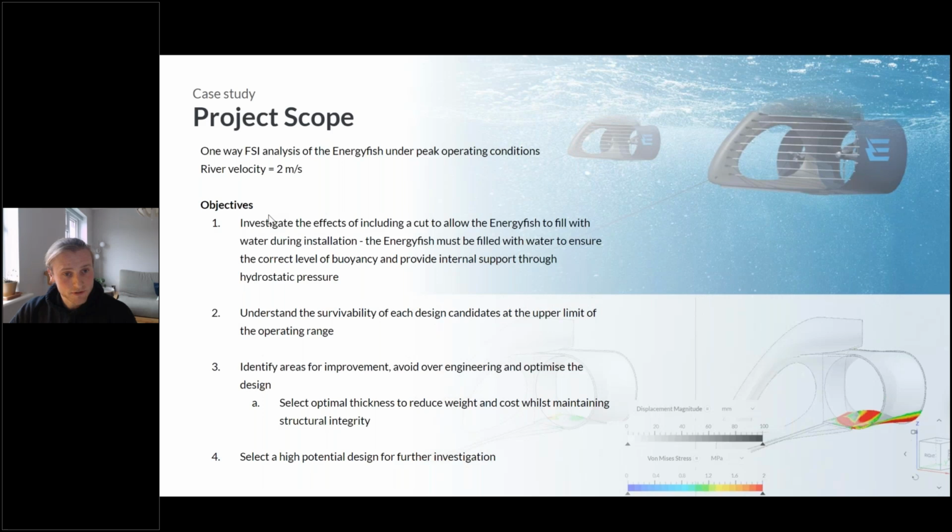Some objectives of the analyses is firstly to investigate what happens to the structural response, the stresses, and the deformations when we include a cut in the Energyfish such that it can fill up with water. Typically when you make a cut somewhere, it's going to increase the flexibility, and it's likely going to increase the stresses as well.